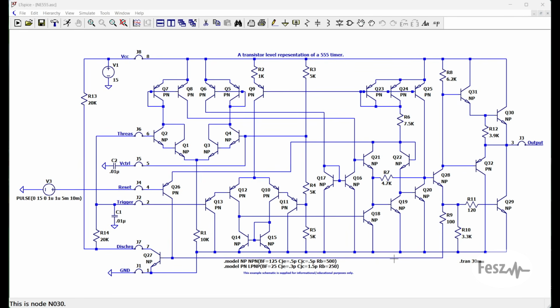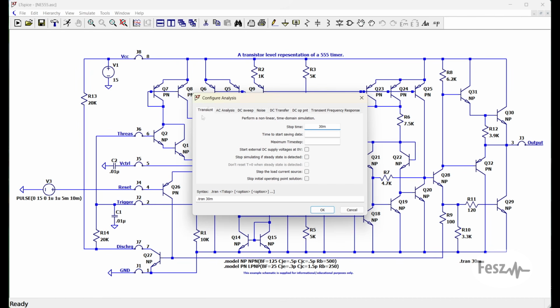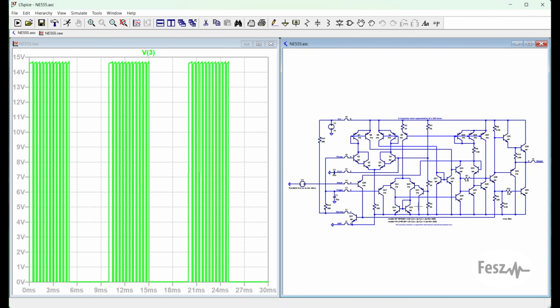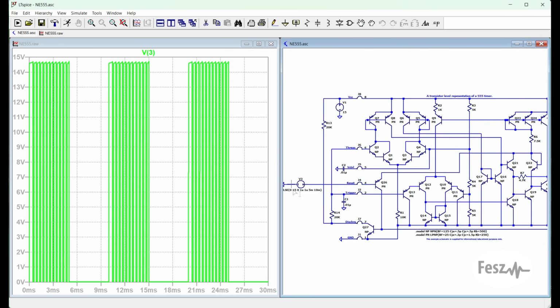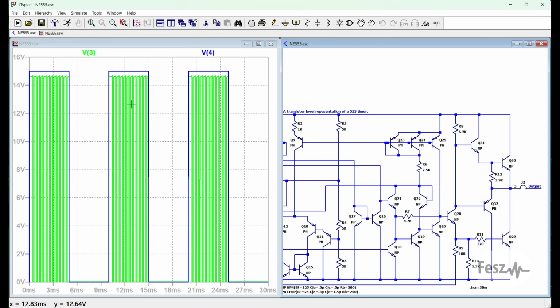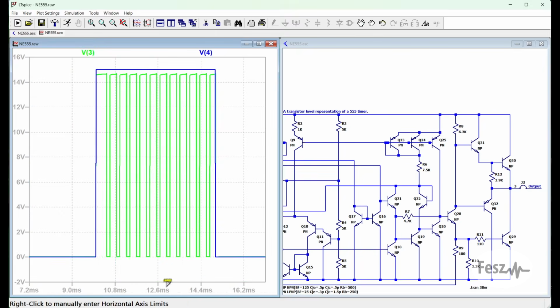So let's start with the two basic types of simulation that you will find yourself using most often. On the one hand, you have the transient type of simulation, a time domain simulation where you analyze the behavior of a circuit over a defined period of time. In this example, we have the 555 timer IC's internal structure, and we apply a square wave on the input, which is then modulated using a higher frequency generated by the IC. So with this type of analysis, we can easily see how a circuit evolves over time and how it passes through various nonlinear states.